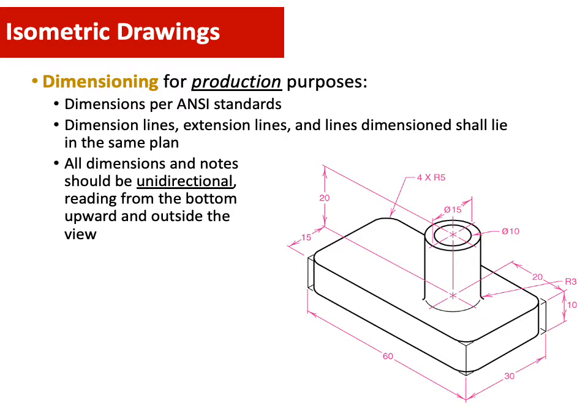Also note that all dimensions should be unidirectional, reading from the bottom, and outside of the views. So all the dimensions are put outside of the object, and they also need to be unidirectional. If you want to know this section, you can't just put it here.